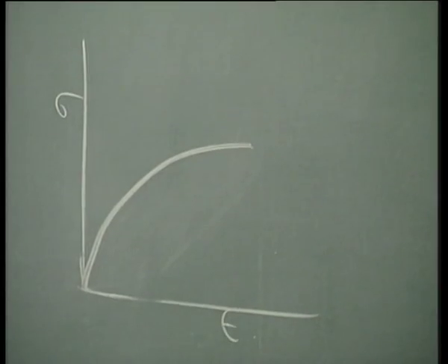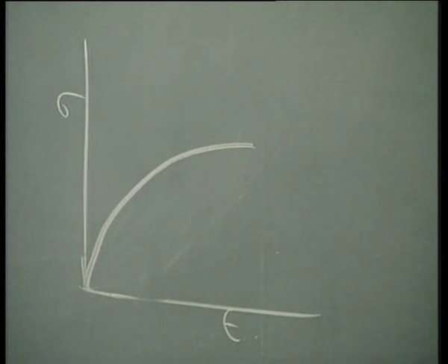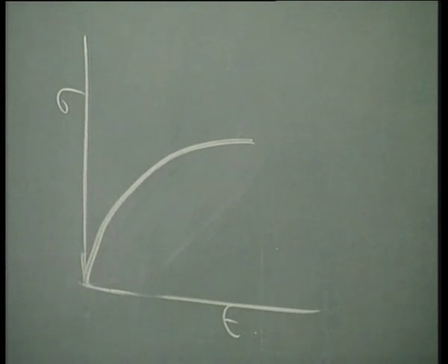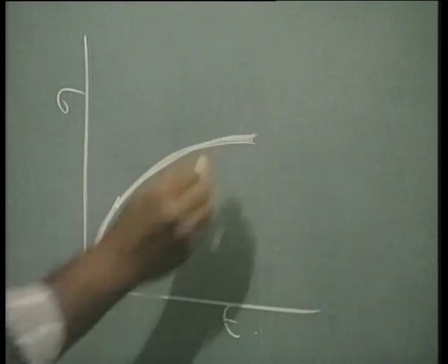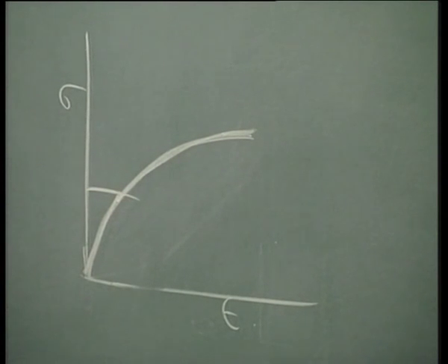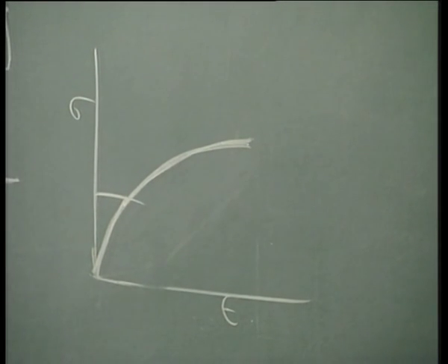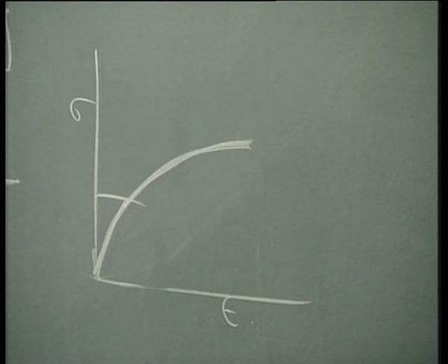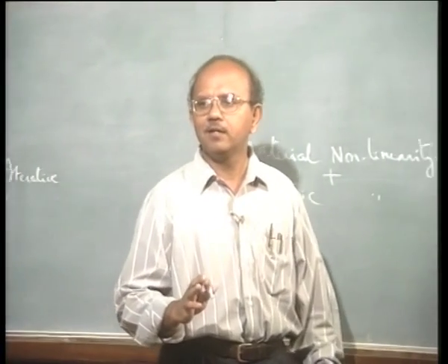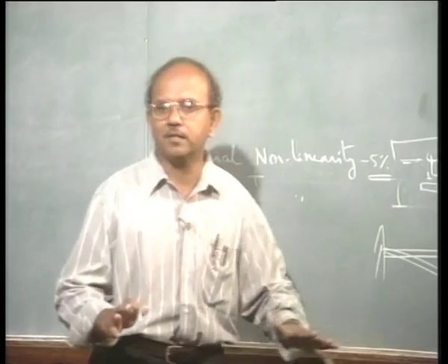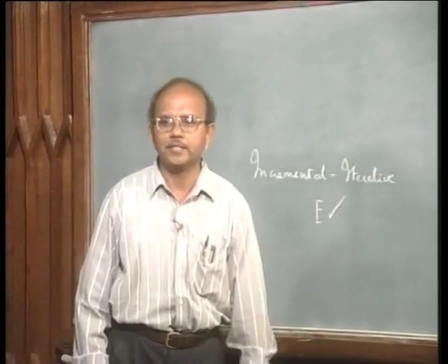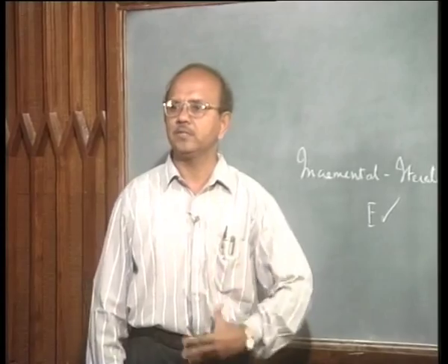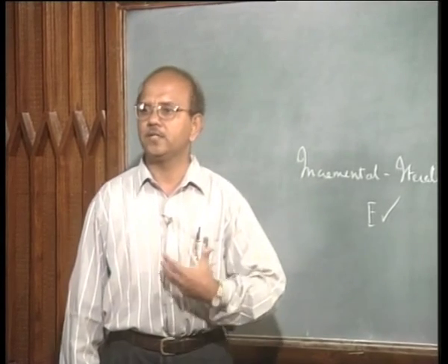Let us take a curve like that, for example, a stress strain curve for a material, say metal, and let us say that this is yielding, so this is straight, and then this hardening and so on. So, that is the yield point. Okay. Let us see how to do this problem. You understand? The issue is E for the elastic material which we have done so far is constant, and now the slope varies, as you correctly said, with respect to the strains, and so my approach has to be entirely different.